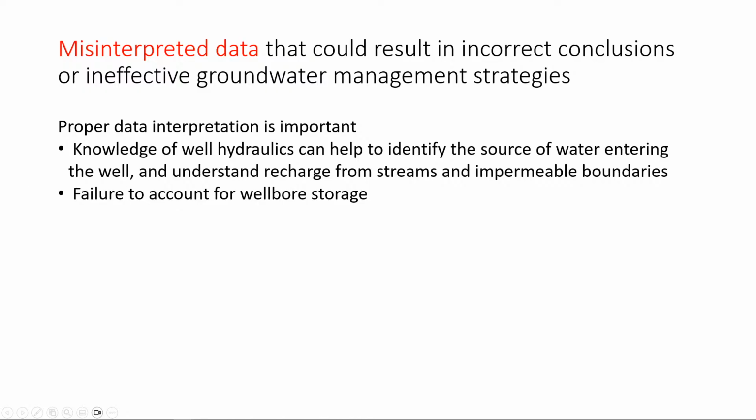So, failure to account for well bore storage. We talked about well bore storage and the failure to account for this. If the effect of well bore storage is not accounted for, that may result in misinterpretation, where the hydraulic conductivity you estimate could be very different from the hydraulic conductivity of the actual formation.